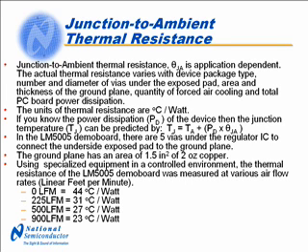If you know the power dissipated in the device, then the junction temperature can be predicted as Tj equals Ta, the ambient temperature, plus the product of the power dissipation times the theta JA.